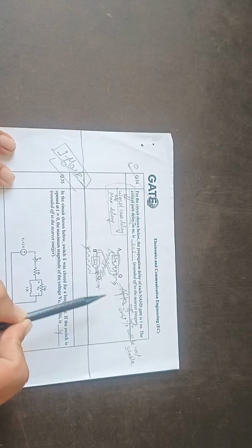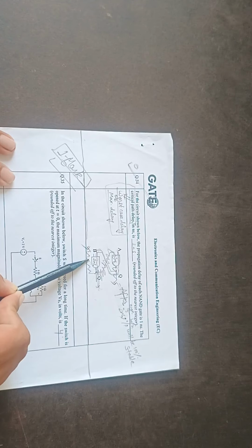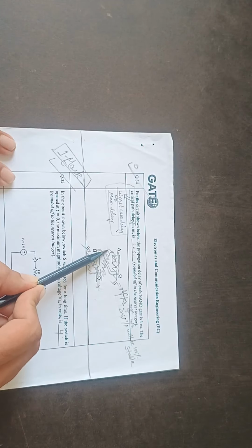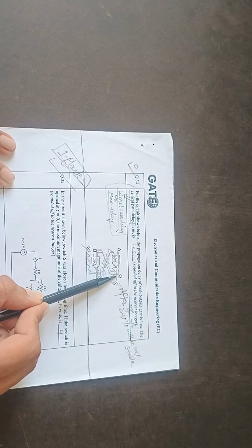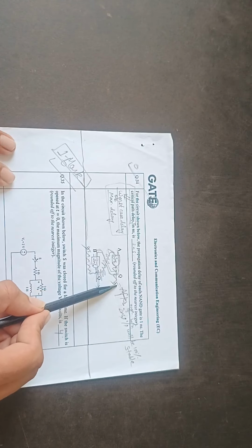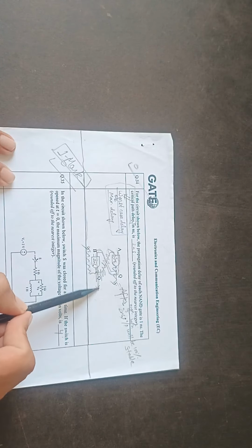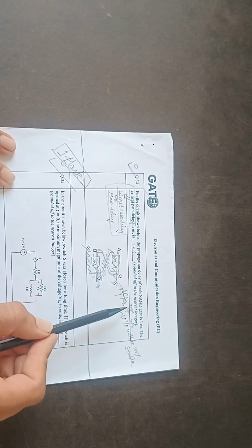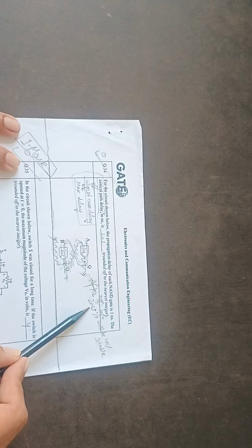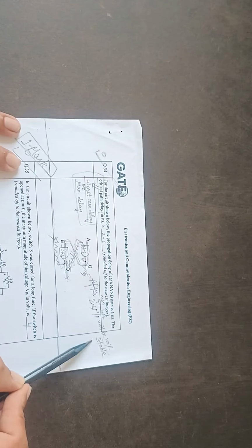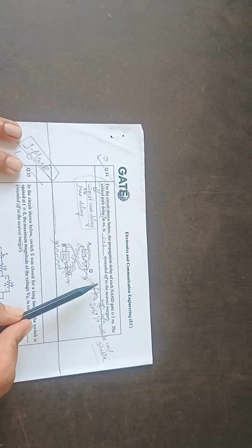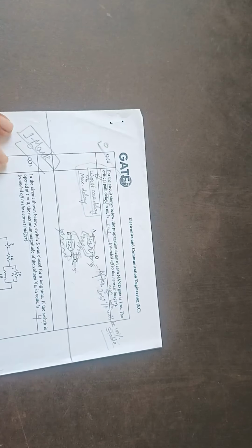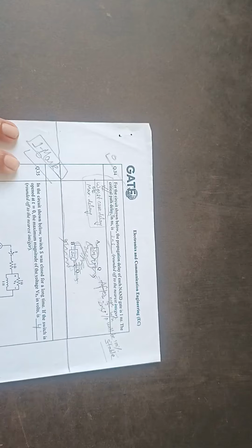Okay, similarly if there is some input at B, then it will go after 1 nanosecond here, then it will go here, and then after 1 nanosecond, after multiplying with this, it will come out. So no matter whether it goes here like this or here like this, after a maximum of 2 nanosecond both outputs will be 100% stable. So we can say that the critical path delay of the circuit is 2 nanosecond. Okay, again easy question.